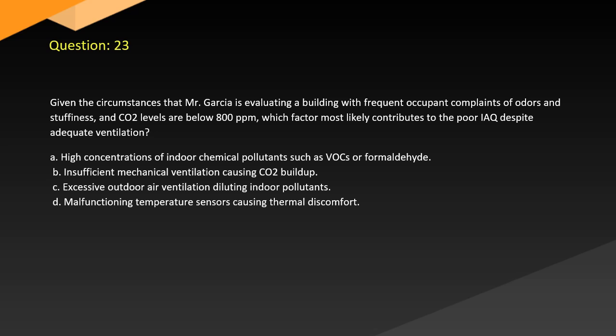Question 23. Given the circumstances that Mr. Garcia is evaluating, a building with frequent occupant complaints of odors and stuffiness and CO2 levels below 800 ppm, which factor most likely contributes to the poor IAQ despite adequate ventilation? A. High concentrations of indoor chemical pollutants such as VOCs or formaldehyde. B. Insufficient mechanical ventilation causing CO2 buildup. C. Excessive outdoor air ventilation diluting indoor pollutants. D. Malfunctioning temperature sensors causing thermal discomfort.